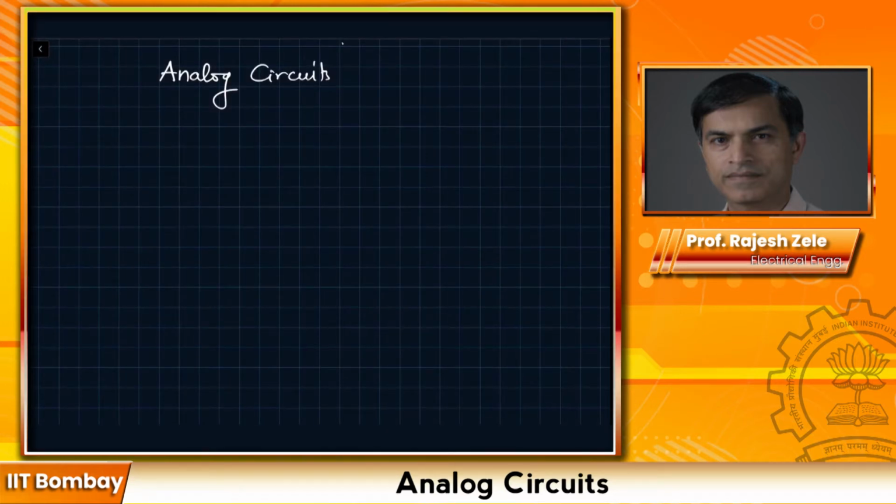It's important that you understand single transistor amplifiers very well. Then you can do complex amplifier circuits very easily. When we talked about the common emitter or common source amplifier, it was the emitter or the source terminal which was common between input and output. Today's lecture, we will start with the common base amplifier. As the name suggests, the base terminal will be common between input and output. What this means is that the input is applied between emitter and base, and output is looked at between collector and base.